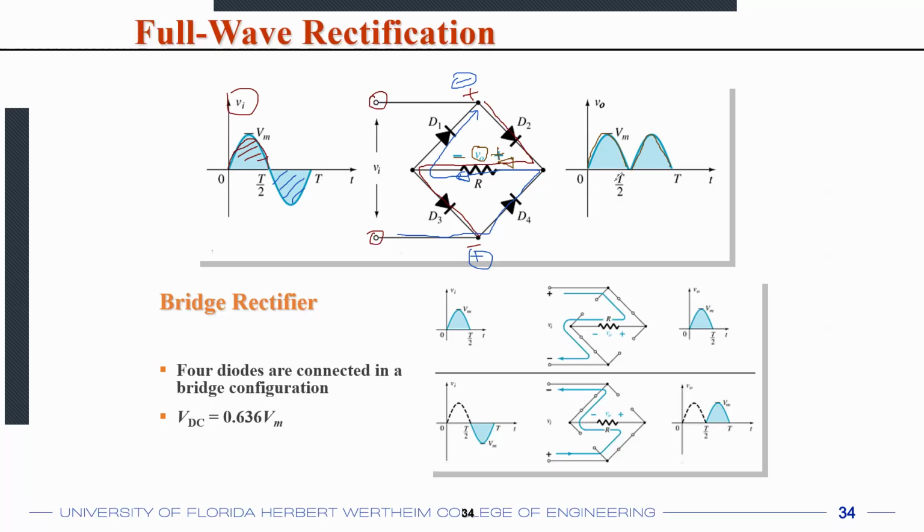That depends on how high of a frequency this diode can support. The diode will not let any frequency pass through it. Just like you saw that the op-amp has a low-pass filter kind of response, any circuit in general has a low-pass kind of behavior because you have a finite bandwidth. You cannot really get a terahertz signal through a diode, right? So it will be some kilohertz to megahertz to tens of megahertz. After that, you'll see that the diode does not even work, and in that case, you'll not see this response from the diode. So depending on the bandwidth that the diode supports, you can use that for AC rectification.